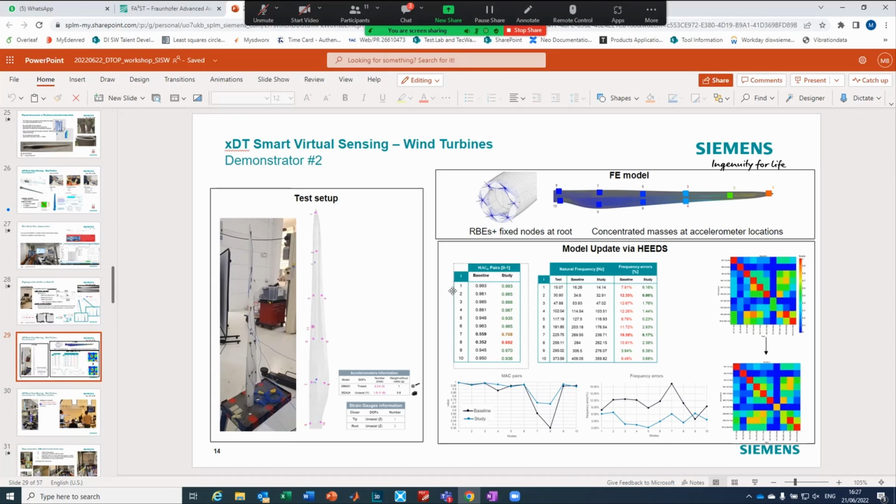So we run this type of activity, sometimes changing boundary conditions and optimizing or changing the model. One of the ideas could be to do that continuously along the lifetime, meaning that you have this blade running for months through these fatigue cycles, and you keep updating the model all along the test. That would be one of the ideas.